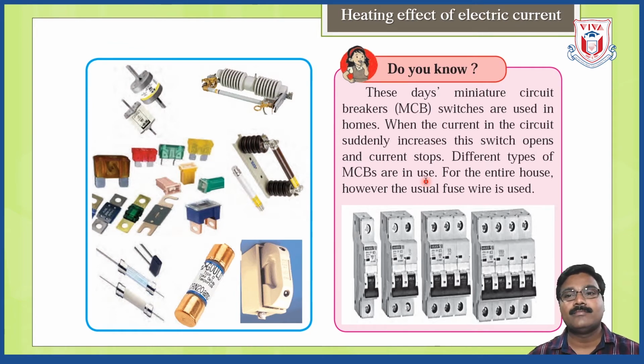The home electrical connection consists of live, neutral and earth wires. The live and the neutral wires have a potential difference of 220 volt, and the earth is connected to ground. Due to a fault in the equipment or if the plastic coating on the live and the neutral wire gives way, the two wires get connected.